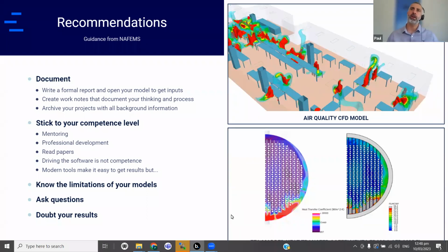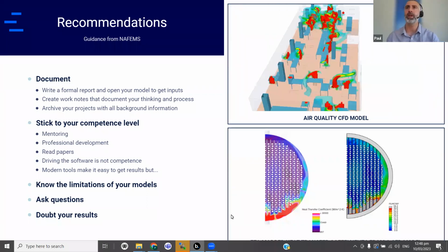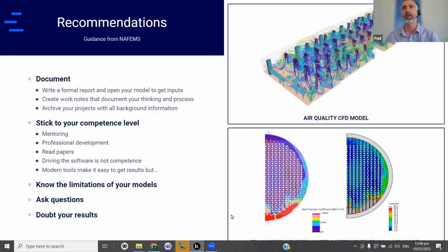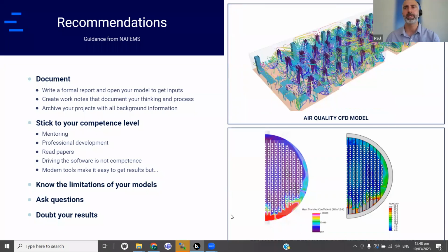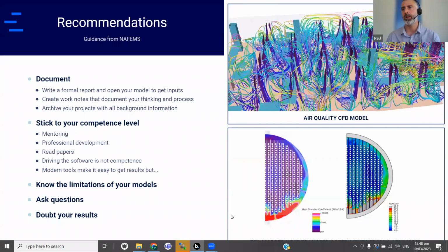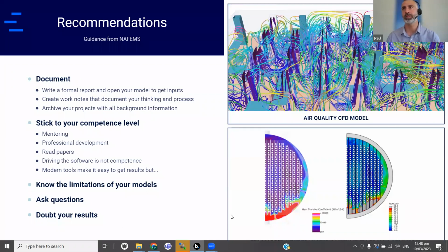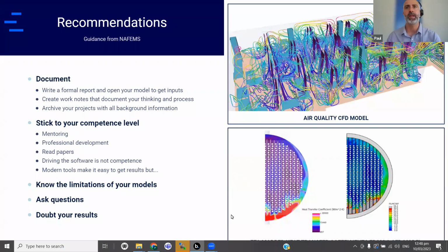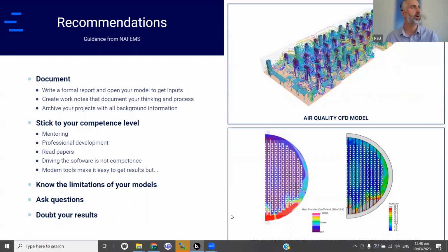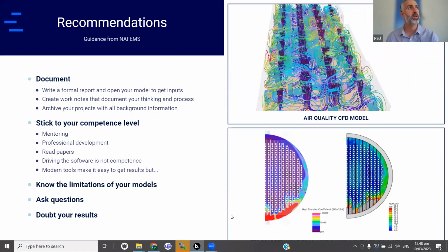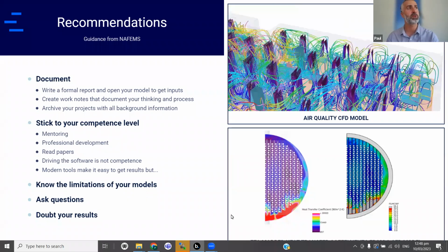I think it was a few years ago now, but I was involved in quite a large project where people had installed pumps and there was a lot of aeration and cavitation on the pumps. And when I analyzed the pumps, it was pretty obvious that there was some pretty poor flow quality entering the pump. So there is a code, the ANSI/HI 9.8 pump intake design code, which provides some good recommendations on the flow quality entering the pumps.